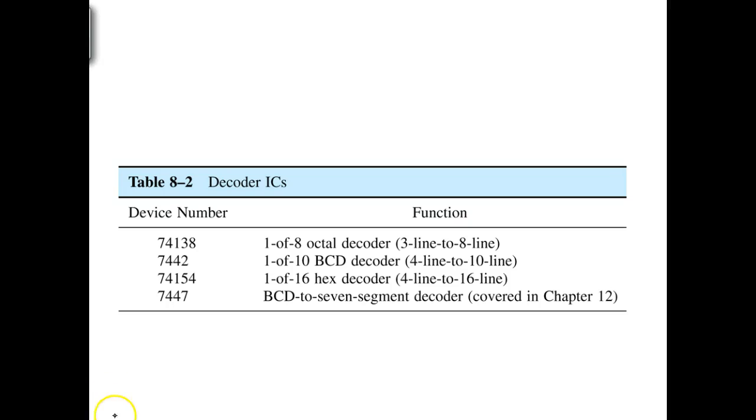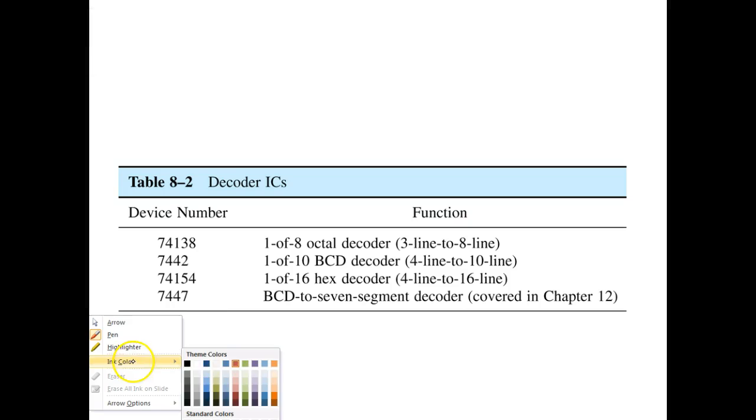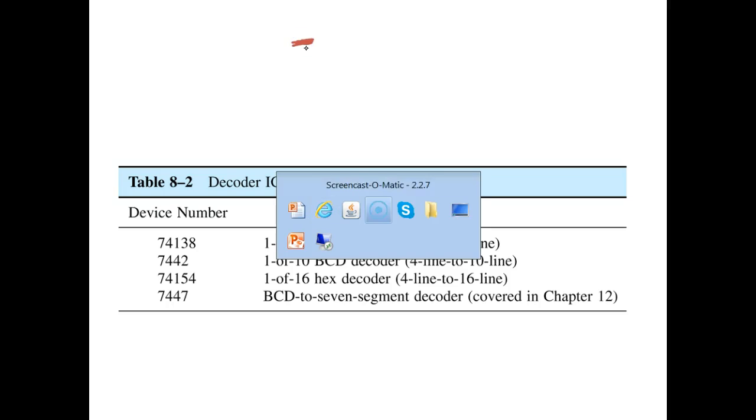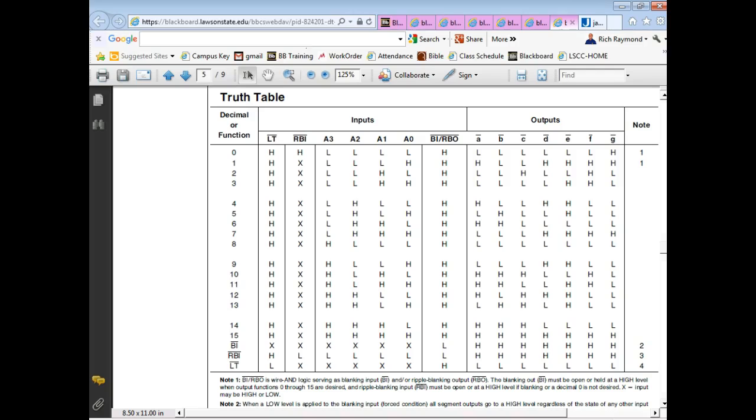So it's going to turn on the A segment. Where's the A segment at? It's across the top, right? Can y'all see that? Yeah, because it's low active. We're using common anodes. That gets people confused. So common anodes, we turn those on with lows. Common cathodes, we turn those on with what? Highs. So this says A is going to be on.